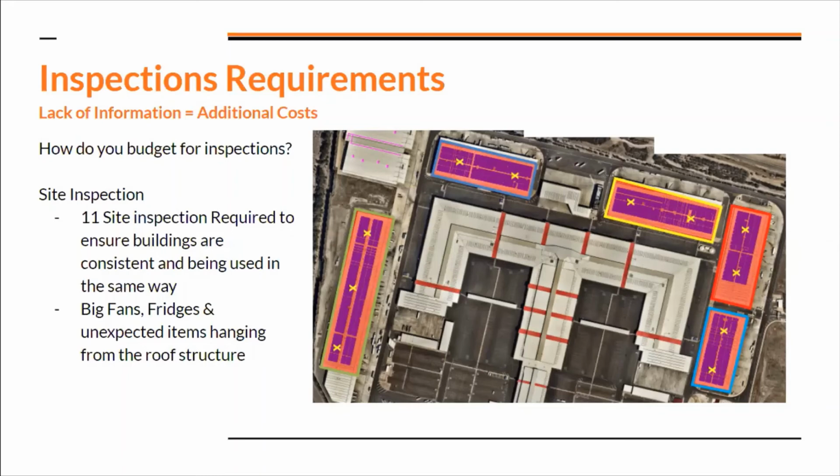And lastly, I want to make a point about if there are big fans, and ceiling tiles and fridge tiles, that doesn't mean it's not going to work. It just means we hope that the building's been designed for those types of loads. If there are massive fans, which we see in Queensland a lot of the time, the design engineer initially designing the building took those massive fans into account. So now the additional weight of 15 kilogram panels isn't going to blow the budget. You know what I mean? It's not going to push it over the deflection limits of the building. So it still can be more than fine, but we just need to know now, and we need to understand why it's coming up like that.